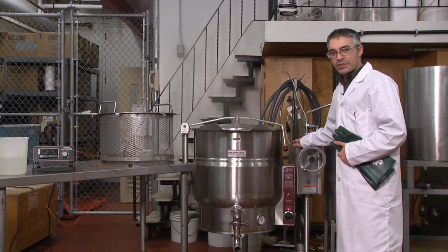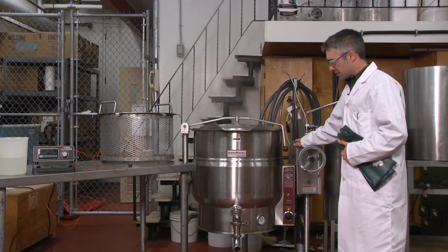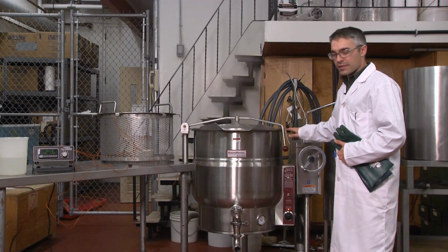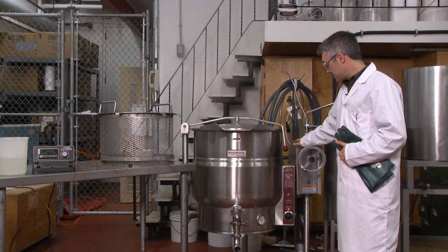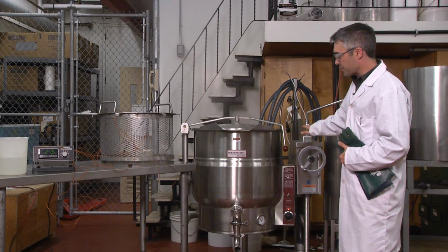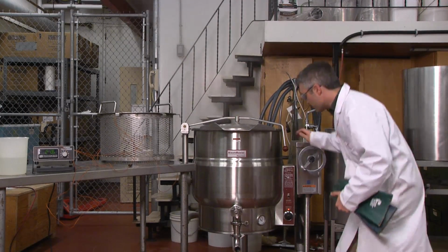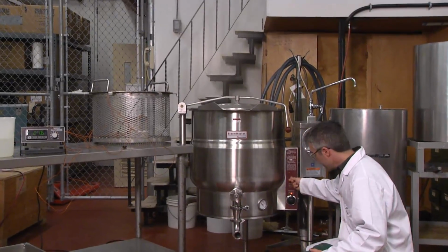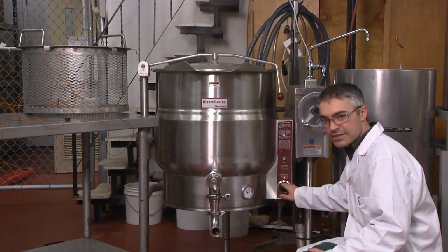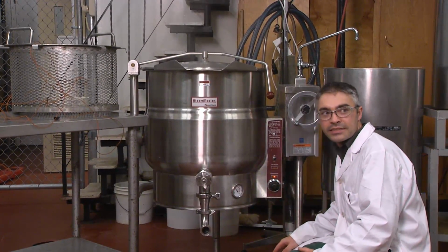When you come into the laboratory, the apparatus should be already started, because it takes a bit of time to bring the water up to boiling. However, if you are the TA, or if you're coming into a cool water laboratory, you must first turn on the main power switch for the kettle, which is located on the wall behind me. Secondly, you must turn on the main power here and set a set point here for the temperature. This is not an engineering scale. It is simply a relative 0 to 10.